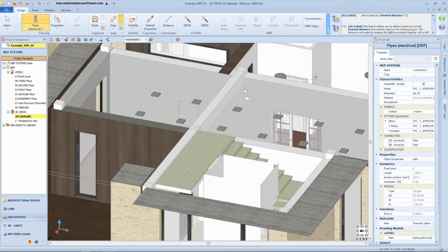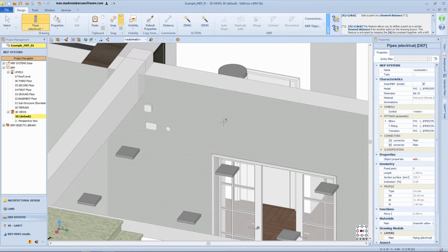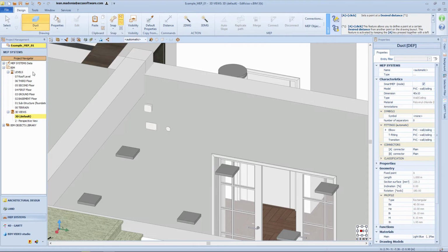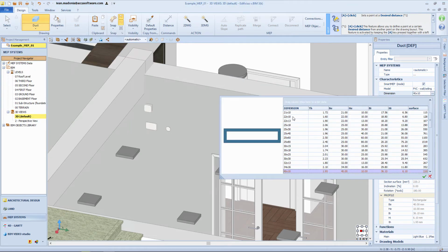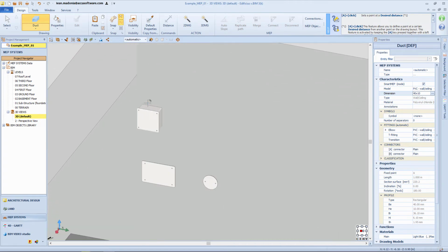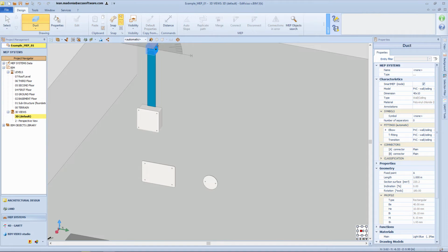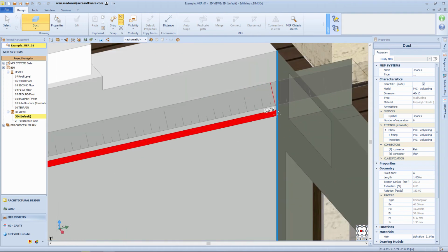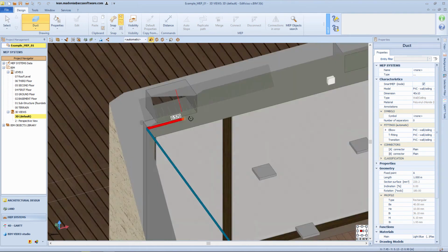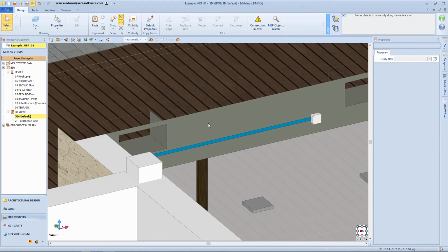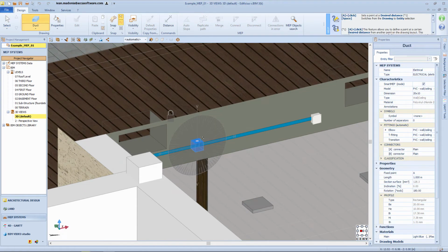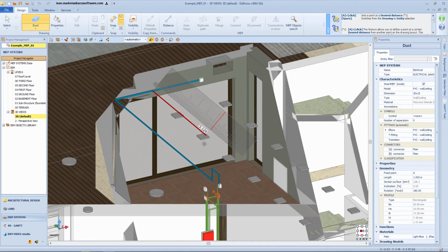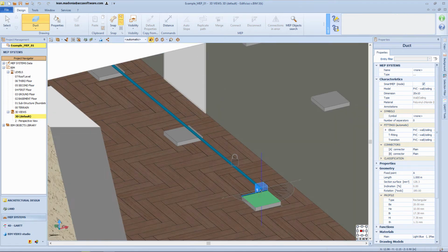From the drawing menu, you can then select the duct connection entity to make the connections between the exposed junction box and the lighting device points. From the Properties toolbox, simply choose the element with dimensions 40 by 10. With a mouse button click, you can start to trace the duct using the directional cube as a tracing aid, together with the protractor and ruler. The connection is then traced between the visible junction boxes and then with the light point entities.